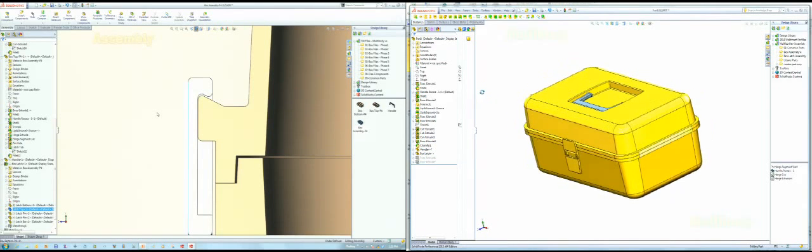So here it is, and when we brought it in, all the bodies came in. Now, the difference is I positioned it with the constraints like you saw before, but I can't make that lower boss and then remate it. In other words, he could make the boss and then remate his part wherever he wanted to because there wasn't any order in the assembly mates. But we have features here, so we bring in the box latch and then we create the boss, and I can just show you how he did that.